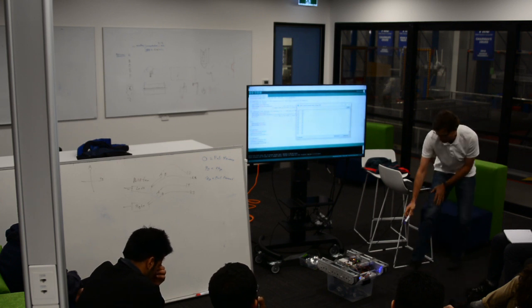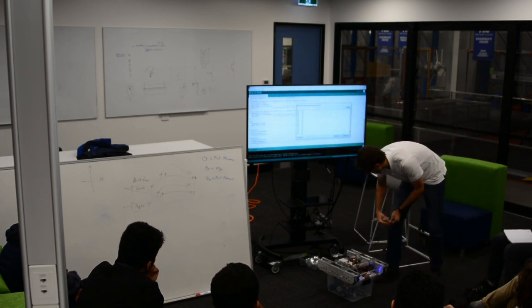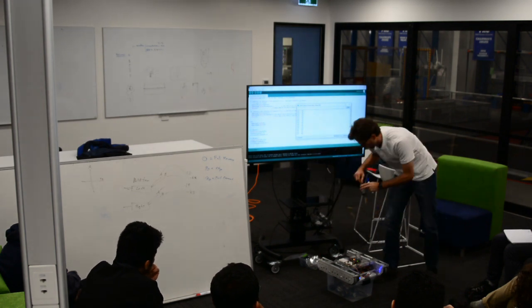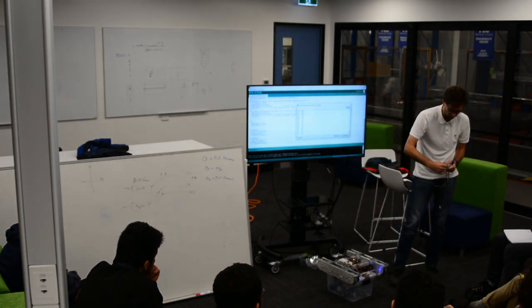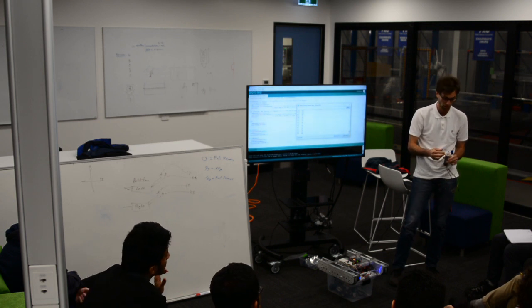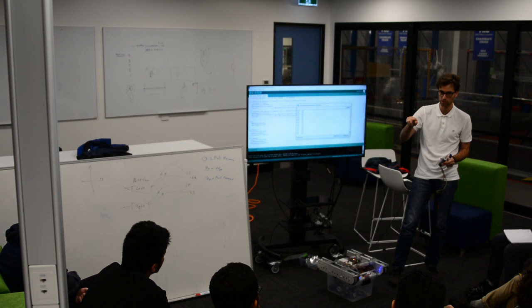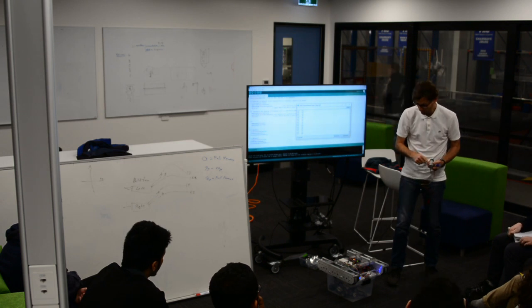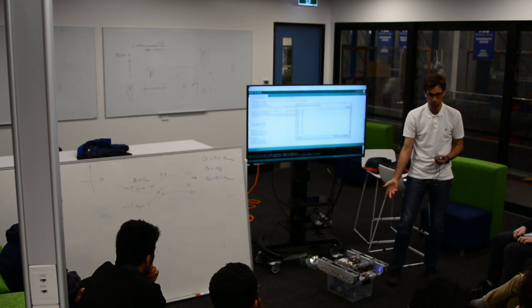Is there one belt that's a bit tighter than the other one, or whatever it is? But it can be, one of the things that can cause it is, on these motors, this is getting a bit beyond for you guys, but I've seen it a lot where if you put too long a screw in the face, you bend the gearbox, and then you add a whole bunch of internal friction to the gearbox. It's actually kind of hard to see unless you slowly increase the throttle and see when it turns on. But that's the very beginning of where it could occur.